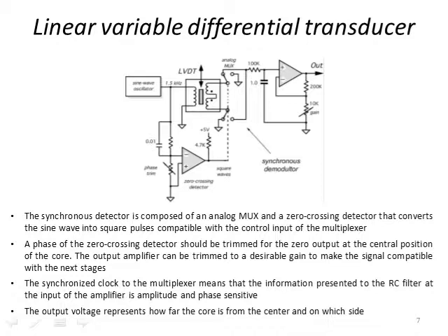And this circuit then demodulates the motion of the central core. So then you will get a voltage that's just a function of the displacement without this modulating sine signal from this operation. This is a really interesting and simple way to do it, and it can be quite an accurate way as well to be able to modulate the movement with an AC signal and then demodulate it. And we've seen some of this synchronous demodulation in one of our earlier lectures and also in our homework.